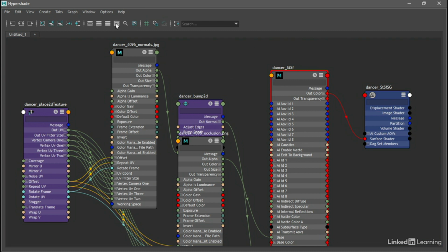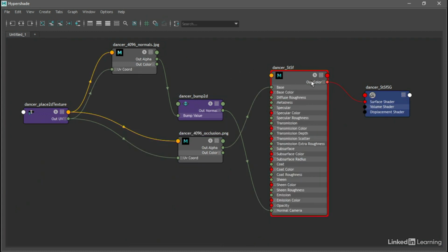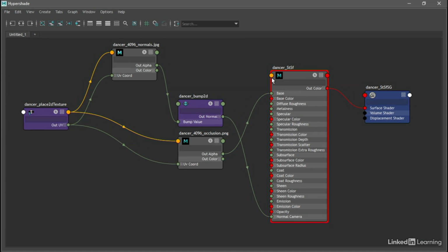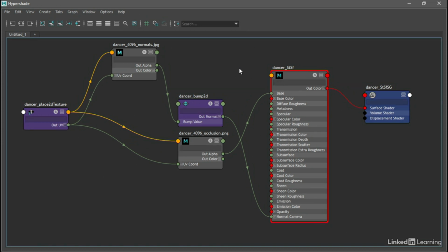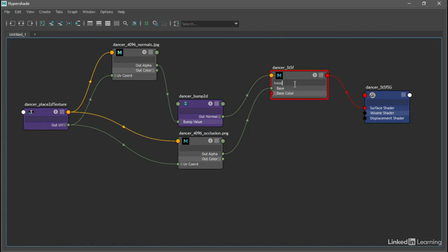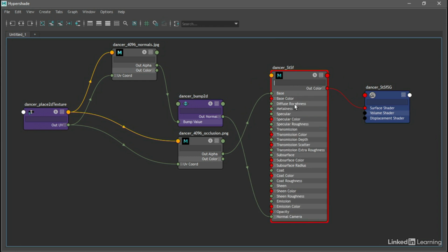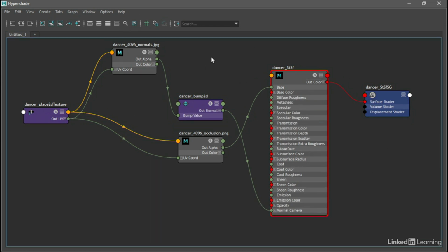If we're in custom attribute display mode, then that field disappears up here. But we can actually bring that back by clicking on the magnifier glass here. Toggle the display of the attribute filter field. And now we can go back to searching once again, BASE, and everything that doesn't have that string in it is hidden. All right, I'll erase that and switch that back off again. That's how to filter the display of nodes and attributes.